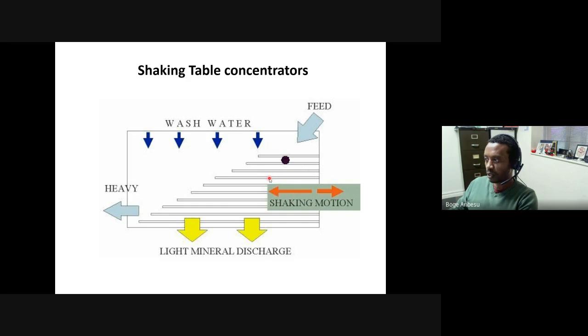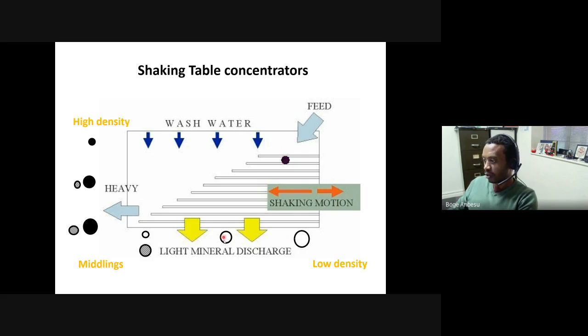They come to the next one. Here we have denser particles again at the bottom, light ones at the top, then top ones which are light will be washed, and eventually light particles should come somewhere here. Okay, so light particles will be collected somewhere here, or in this case, low density particles. If they're really large, light particles, then it's easier to wash them because they roll easily. You can actually wash them very easily. And usually large, low density particles are presented to the table somewhere here. So we can collect them here. So these are typically gangue, okay, the waste rock.